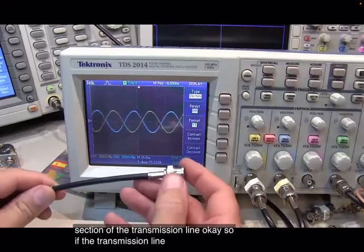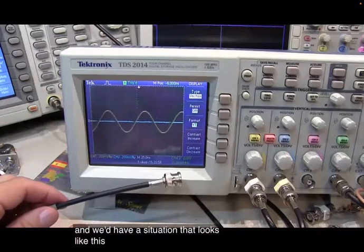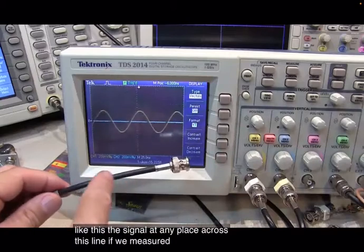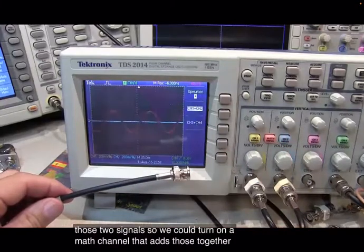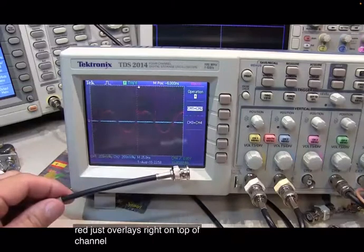So if the transmission line was perfectly terminated, we'd have no reflected signal, and we'd have a situation that looks like this. The signal at any place across this line, if we measured its amplitude or its power, would simply be the sum of those two signals. So we could turn on a math channel that adds those together, and we can see the math channel, which is red, just overlays right on top of channel 1.